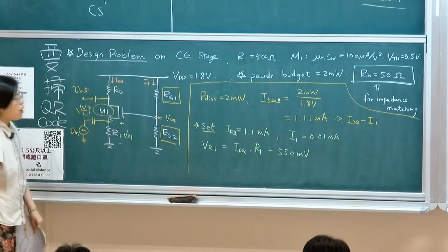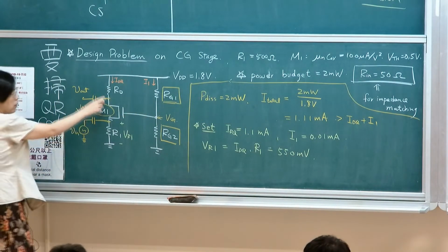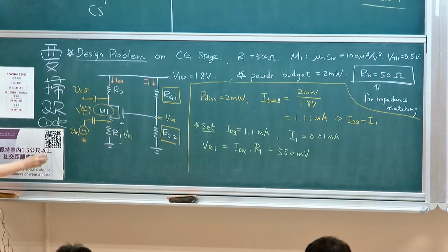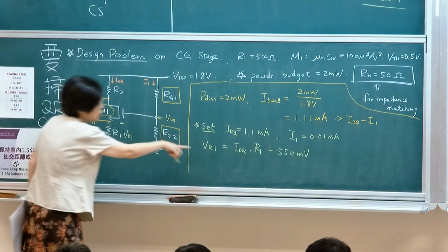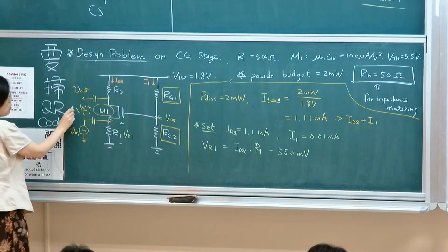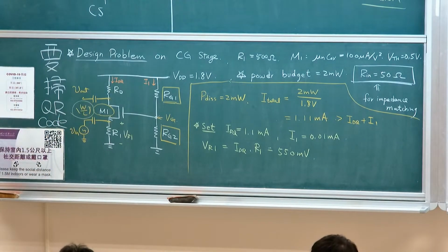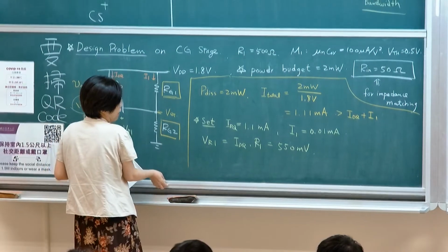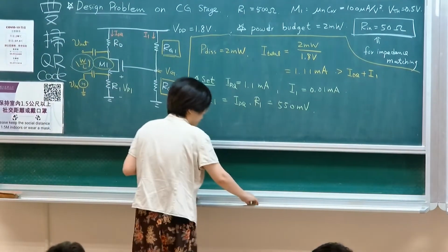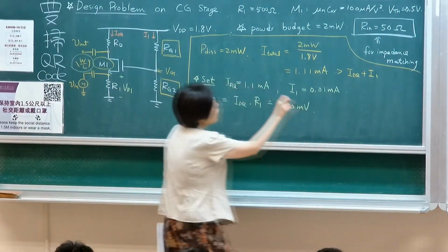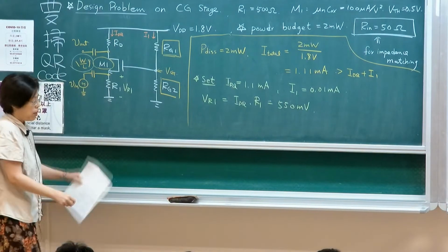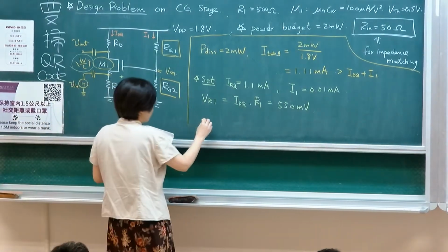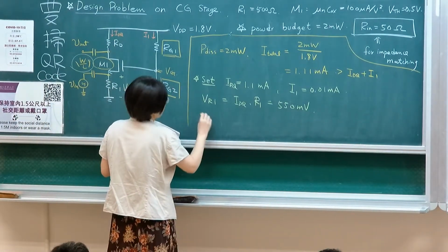Okay, so I already know the current. The other thing I need to determine, now that these are defined, is W over L. Before determining W over L, you should know how one determines it. You start with your requirement on GM. So we know Rin, I should say.